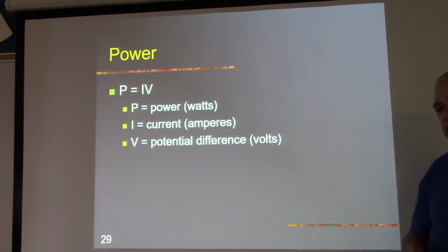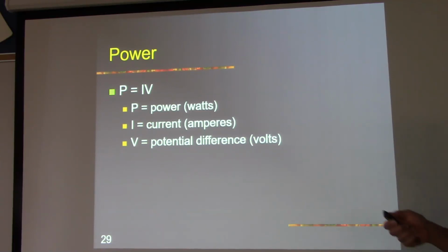So here's a question for you. Suppose I have a system that's capable of 1,000 milliamps at 80 kVp. What is the power rating for that system? I'm going to take my 80,000, which is my volts, 80 kV, and multiply that by my current, which is 1,000 milliamps, or 1 amp. So 1 times 80,000 is equal to 80,000, which means this system has 80 kilowatts of power. That's a pretty strong system.